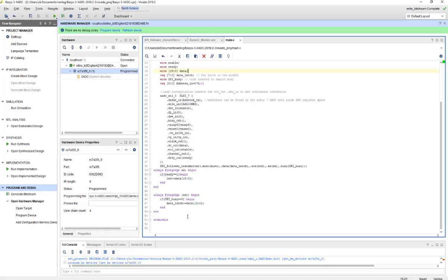because whenever SPI is getting enabled, the SS or CS is getting put down to 0, right? So I was thinking, can I use that signal line whenever it's getting put down? Whenever it's getting put down means SPI will get started. So I'm using that negative edge to trigger the data latch transmission, the data exchange through the data latch. So I'm using the negative edge of the SS, then I'm sending the data to data latch. I was trying to see if that helps.